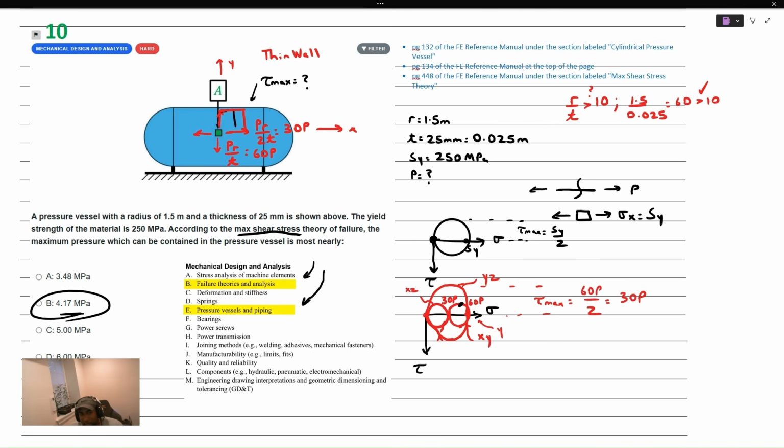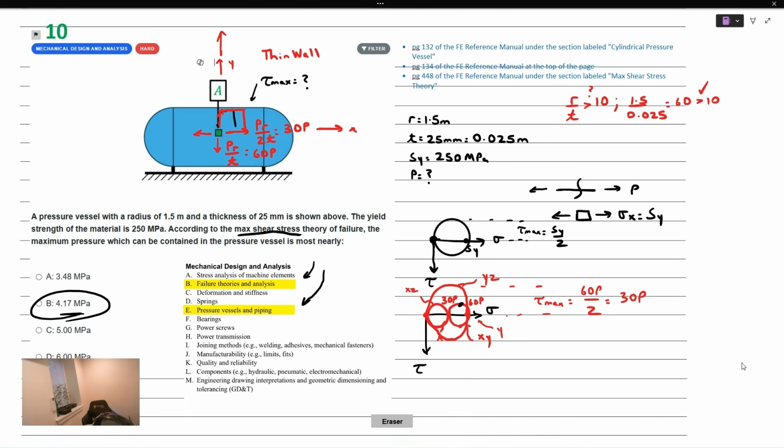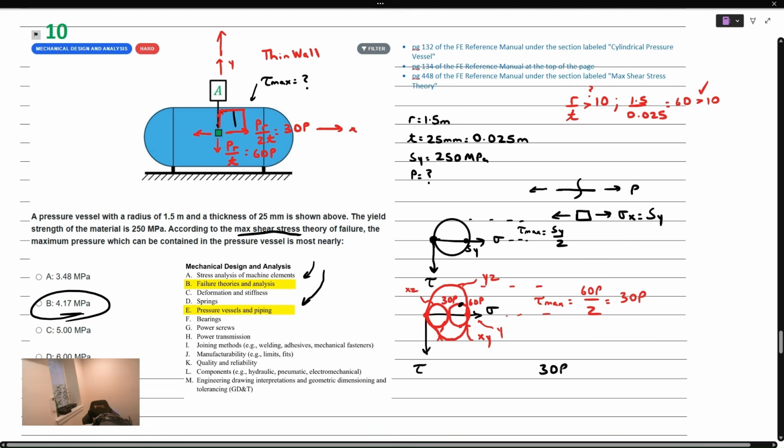Okay, so if we think about the YZ plane, that's this vertical axis and the one out of the page. So technically, the maximum shear is experienced when we rotate around the x-axis. And if you can picture a kind of cut going through the cube, the stress element that would be created on that plane at 45 degrees, that's where we would see this maximum out of plane shear. So it's equal to 30P, and we know that we find the maximum shear stress in this body, it's equal to 30P. Failure is going to occur when we reach that at failure in a simple tensile specimen.